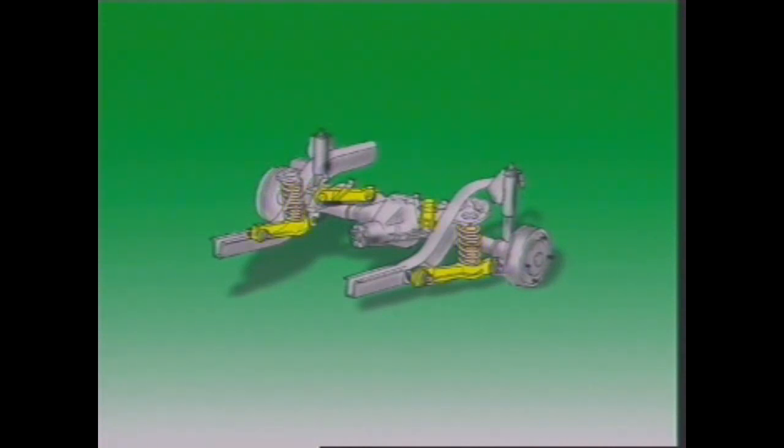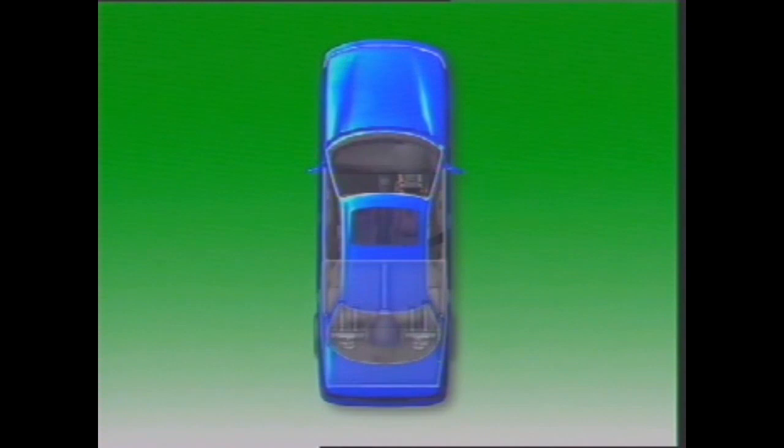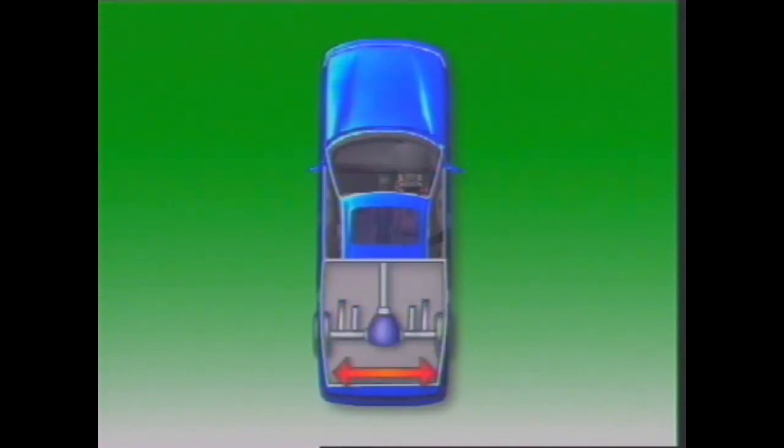Trailing arms or control rods are used to position the axle longitudinally. They have flexible rubber mountings at each end where they locate on the axle housing and on the chassis frame. They would allow the axle to move laterally if it were not restrained. Any such movement has to be controlled to keep correct alignment with the front wheels and the vehicle frame.